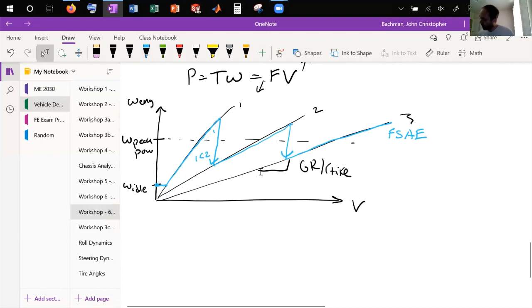Baja, on the other hand, so this slip, right, until they get into gear, and then they come up here, and this is where their CVT hopefully is designed to start slipping. I mean, ideally, Baja would engage at peak torque. Ideally, here you want this to be peak. You'd actually want to engage not at idle, but at peak torque, right? If you could.